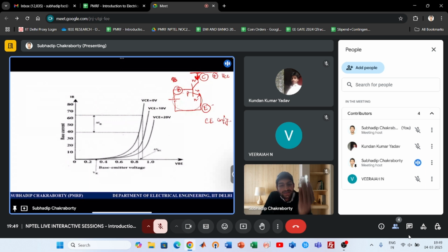But actually you understand for NPN, the electrons are actually the carriers which flow in the opposite direction, just as we saw in the operation. But the current flows from top to bottom because the electrons flow upwards. And similarly, the current flows from P to N, but the electrons flow from N to P. The emitter, highly doped emitter, N to P. Electron flow, so the current flows in this direction. So this arrow actually denotes the type of BJT. So you can easily identify that it is N, P and N. So NPN. And this arrow indicates the direction of flow of current, not the charge carrier.